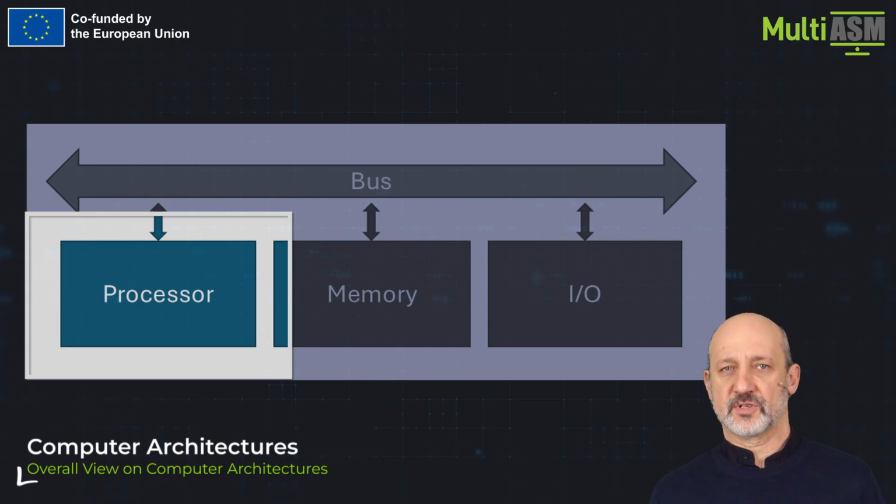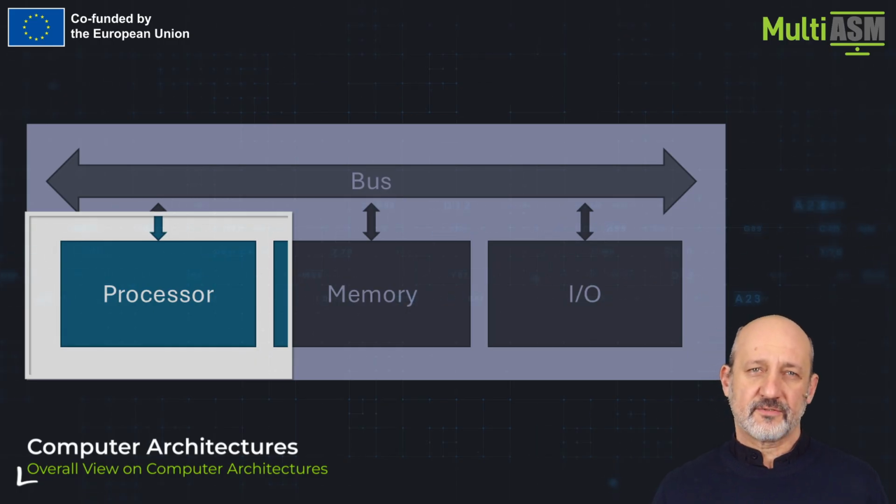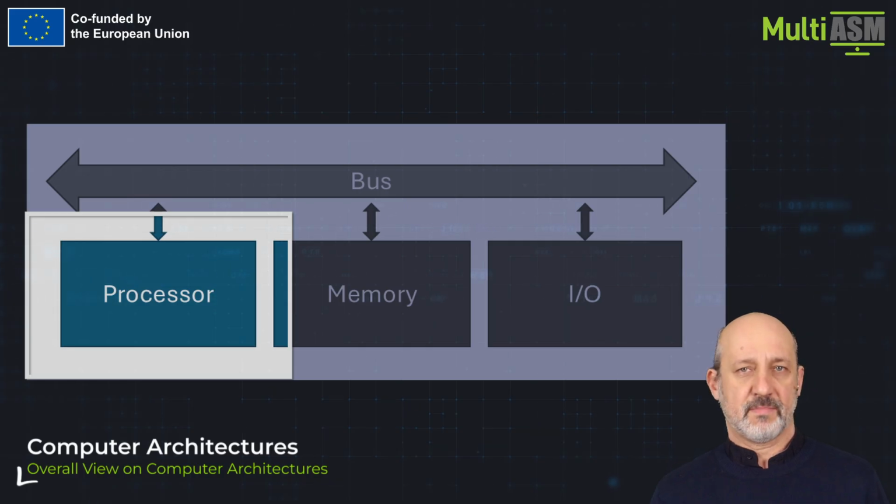The class of the processor determines the size of its internal data registers, the size of arguments of instructions, and the number of lines of the data bus. Modern processors have additional registers which are much longer than the ones in the main set. For example, in x64 architecture, there are ZMM registers of 512 bits in length.